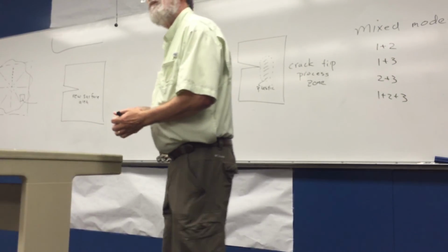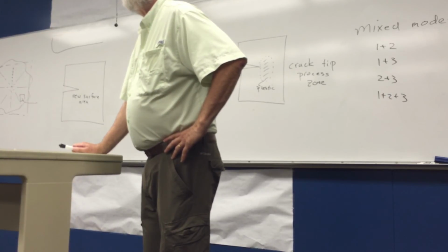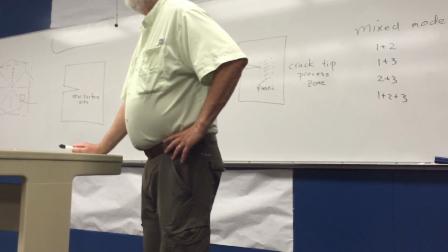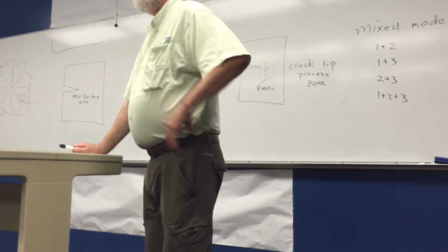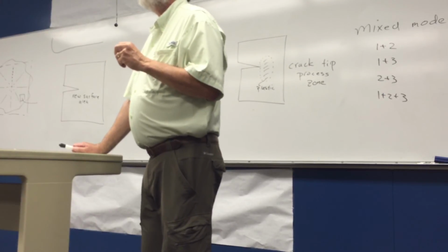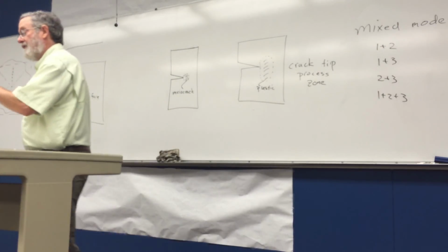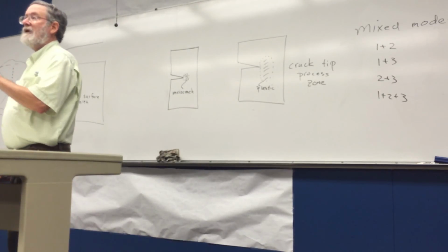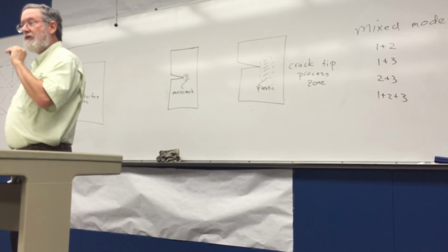Would it be safe to say that based on that, with the zone of plastic yield, if you had a much harder brittle material, you would get a further propagation versus something that's softer? It's good. It depends on how tough the material is. Okay, so it depends on that crack toughness. But yes, in general, if it is brittle, it will tend to propagate further than if it is more ductile.